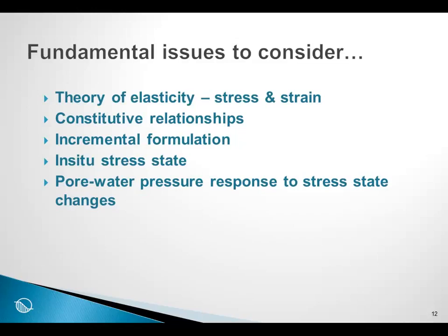In many cases, we need to say something about a state of stress in the ground before we come along as civil engineers and build structures or do something on the ground. As a result, we need to establish the in situ stress state. Sigma W has a special analysis type to establish the stress state in the ground, and then pore pressure response due to stress state changes, which is fundamentally all about a coupled consolidation analysis.